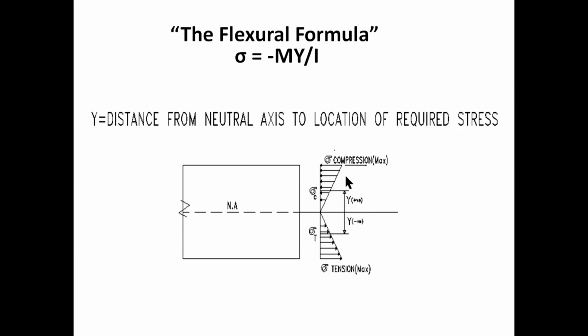If you take y down as positive, then the compression strain at the top of the beam is a positive value. I guess we will discuss this more in detail in the upcoming slides, but either way, the most common sign convention is generally taken as y up being positive and y down is a negative value.